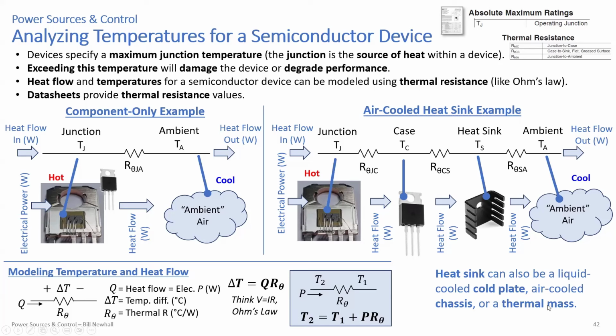So if this device turns on a high power function only every once in a while, you might have some kind of thermal mass, piece of metal, different types of material that absorb that heat for a limited amount of time, and then when the device turns off, that heat slowly gets dissipated. That's good for low duty cycle power applications. Okay, but you could still model everything I talked about there with thermal resistance, again, to get a starting point on a temperature analysis, a thermal analysis.